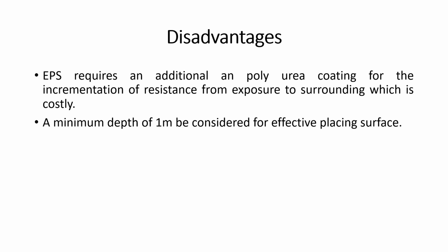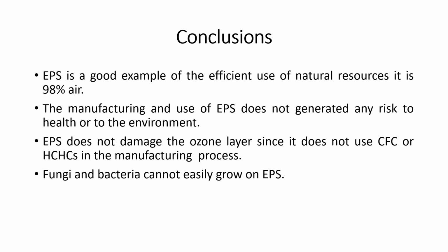Disadvantages of this seminar project. EPS requires an additional polyurea coating to increase resistance to exposure to the surroundings, which is costly. A minimum depth of 1 meter must be considered for effective placing on the surface.